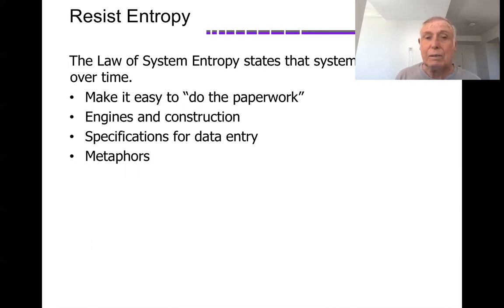Again, this comes from the Bay Area Rapid Transit System. The original structure for managing the electrical network was written in Fortran and assembly code. Try to picture this. You have a track, a piece of track with a third rail. It is powered so that the train can move. Now there's an earthquake or something, or the train breaks down. What you need to do is to take the power off that third rail. So if you imagine a breaker to the left and a breaker to the right, what do you need to do? Well, you need to open both of those breakers, and then the rail is isolated.